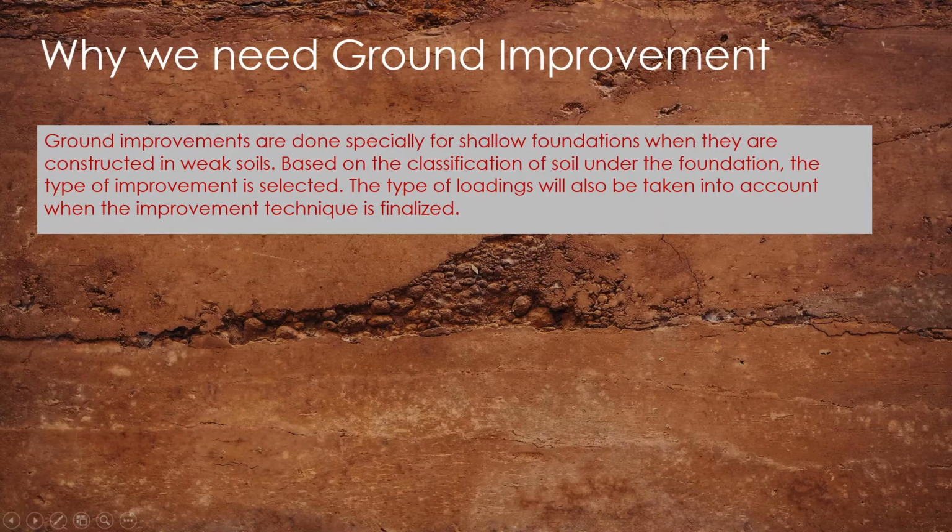Why we need ground improvements? Ground improvements are done especially for the shallow foundation when they are constructed in weak soil. Based on the classification of soil under the foundation, the type of improvement is selected. The type of loading will also be taken into account when finalizing the ground improvement techniques.